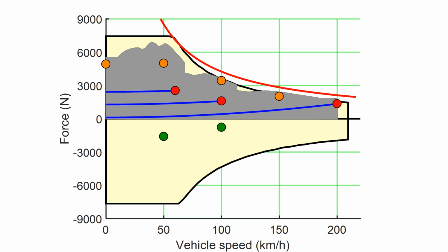At high speed, the combustion engine powertrain can produce higher force than this electric powertrain, since the electric machine then only supplies 85 kilowatt. We can also see that the electric powertrain has the advantage of regenerative braking. Another difference, which is not reflected in the diagram, is that the electric powertrain has a much quicker response when the driver presses the accelerator pedal.